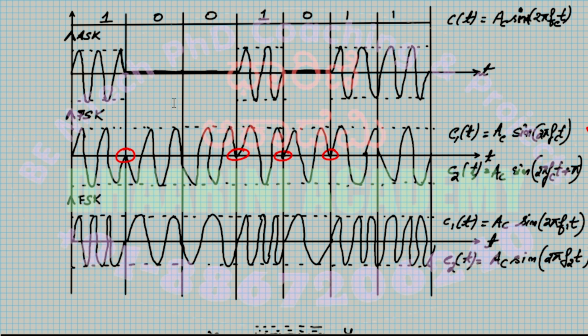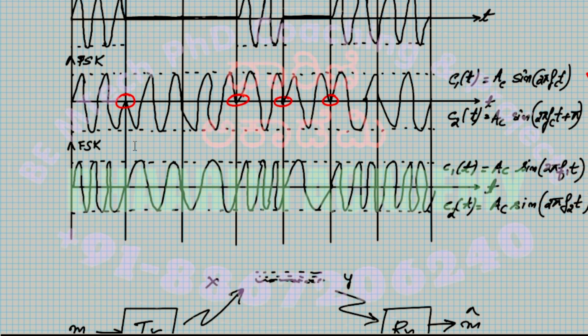Yes, right. So 360 gets divided by the number of symbols. The same logic is applied when you have, say, 4 different signals. That is called QPSK, quadrature PSK, right? So 4 things will get 4 different angles. Okay, so like that, because you divide 360 by 4 and so on. And that is about the PSK waveform.